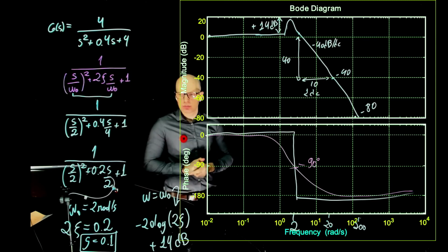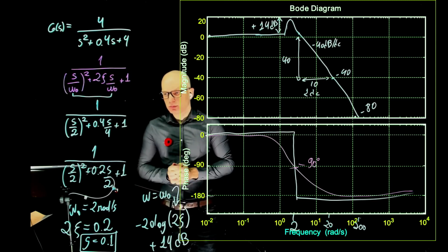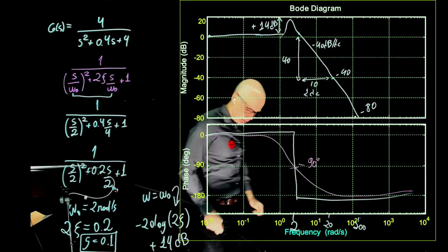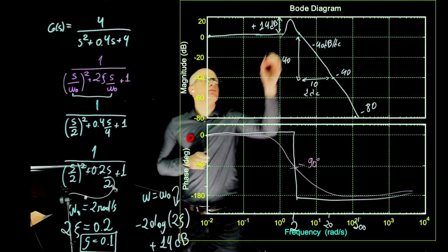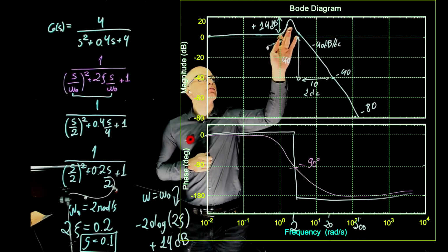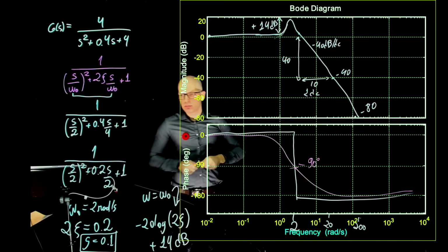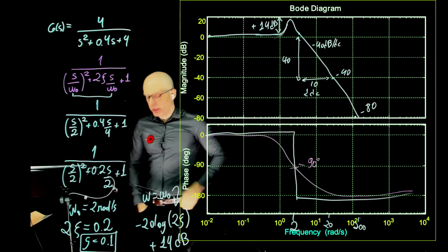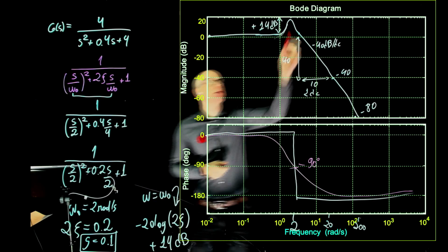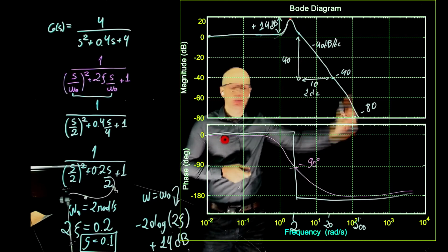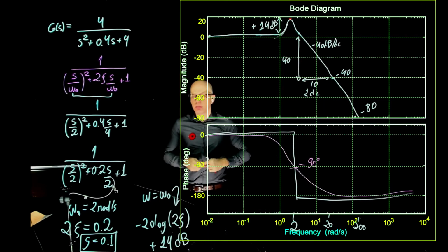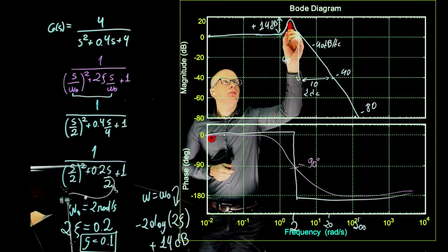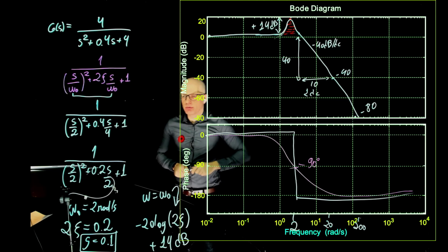So I just have a quick question about the cutoff frequency behavior. At the cutoff frequency, we have our bump, but we will return from the effects of the bump before we head into the effect of the negative 40 dB per decade, right? Right. Otherwise, the slope would start here, and everything would be shifted by 14. But that's not the case. It won't start at the 14 dB point. Now it comes back to where it was before the bump.